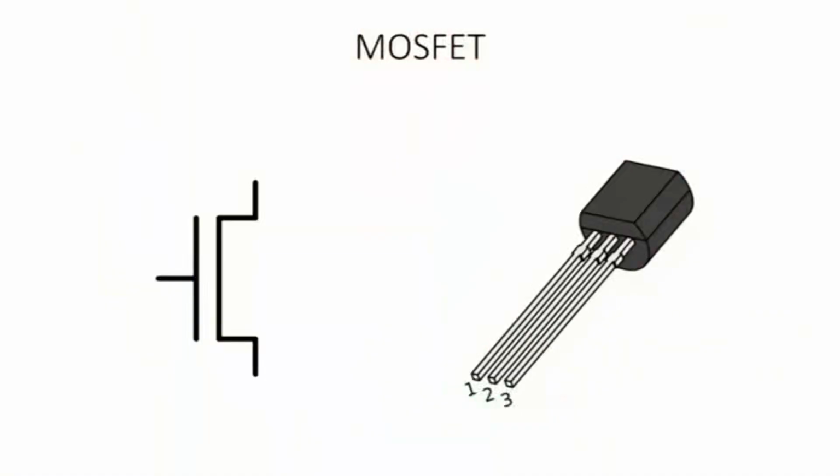So there are multiple types of transistors, and if we want to make digital logic, then we typically only use one, and that's the MOSFET, or the metal oxide semiconductor field effect transistor, which is a ridiculously complicated name, which goes back to how the device is physically constructed and how it physically operates. But all that we need to know from it is that it is a device and that it has three connectors, either on the physical package or on the circuit diagram that you can see on the left, and that there are two main types of it.